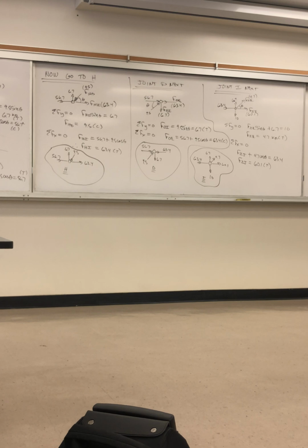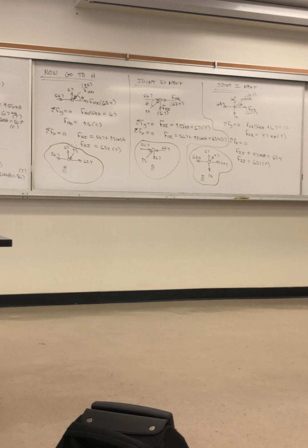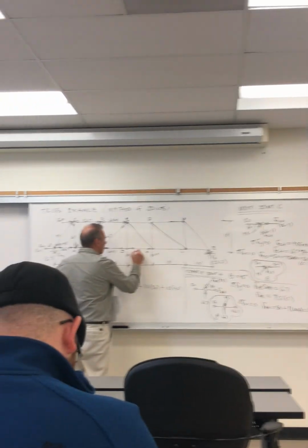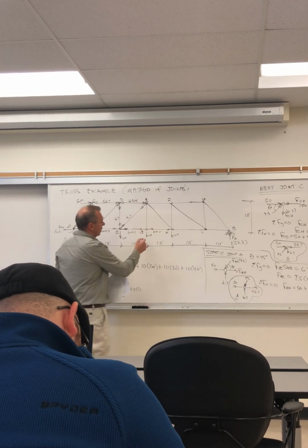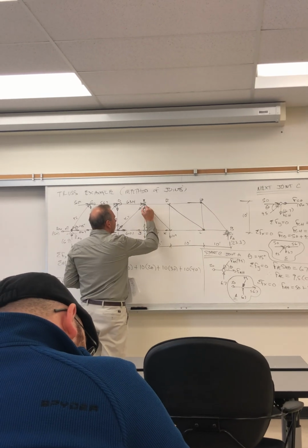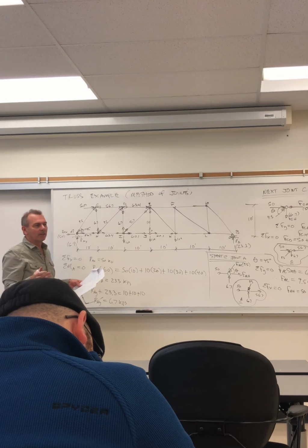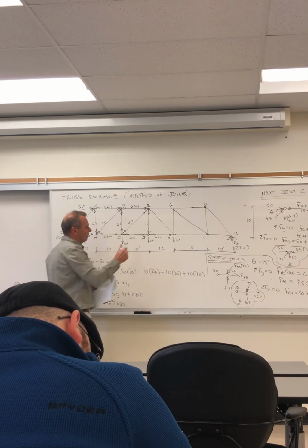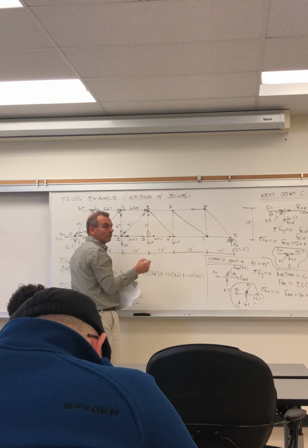J is pretty clear. I won't even write it down. Summation of forces longitudinally, this unknown force is going to just be 60.1, right? It's going to be balanced by that. Summing forces vertically, that 10 will put tension in this 10. So that's joint J. Okay? Everything is just straight. Summing forces, this unknown force JK has to be 60.1, so you can do this unknown.